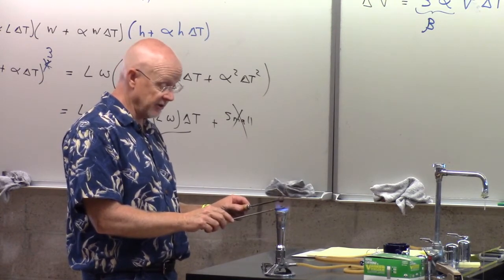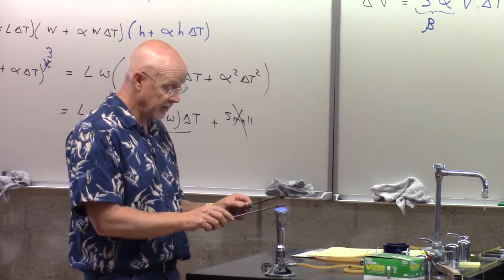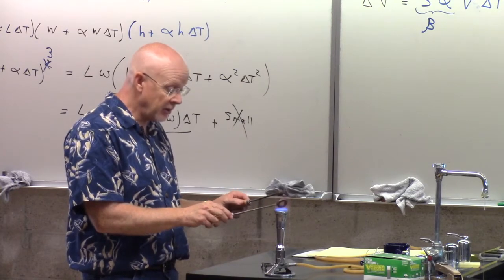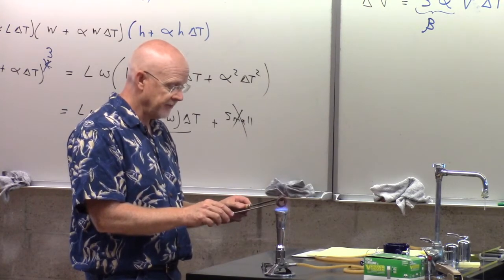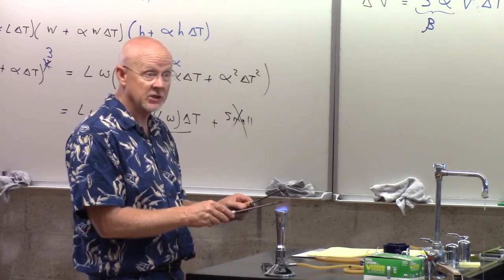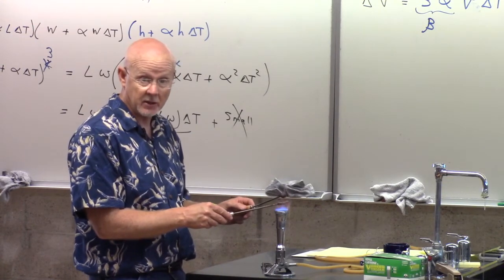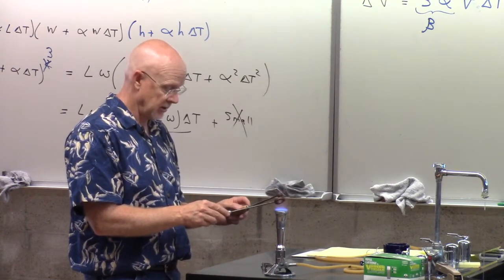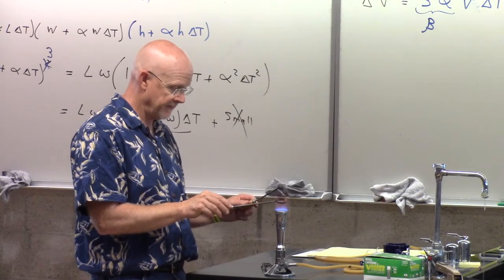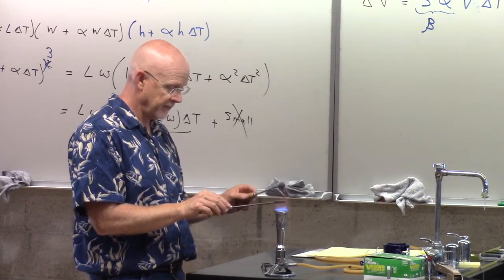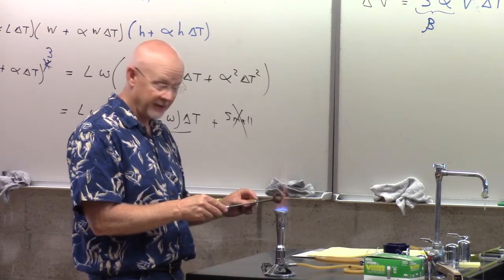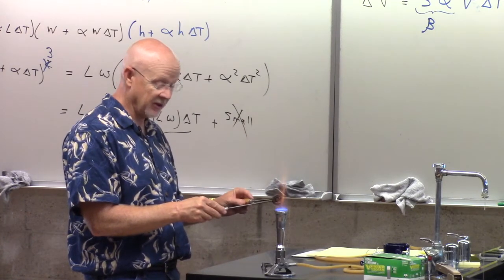Now I'll keep the sphere in here so the sphere stays hot, so the sphere's bigger. But remember my question. My question is, will the hole actually get bigger or smaller? And I want to convince you it gets bigger. I think people's natural reaction is to say it gets smaller. Most people say it gets smaller, but it does not. And so if I have them both warm, not quite there yet. But there it goes. The hole actually gets bigger.